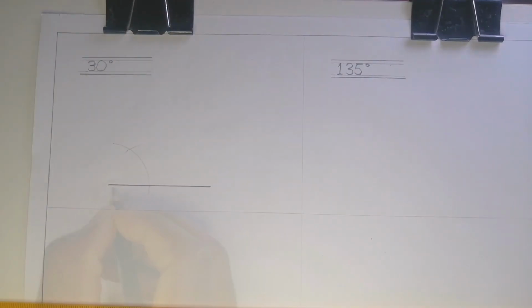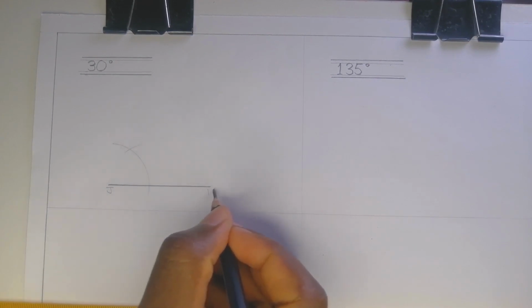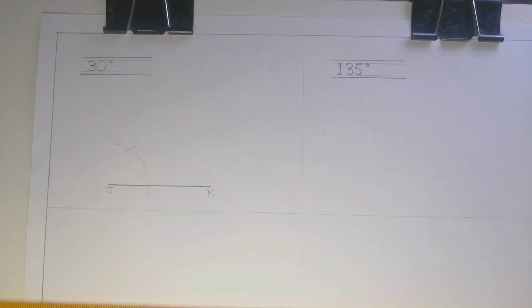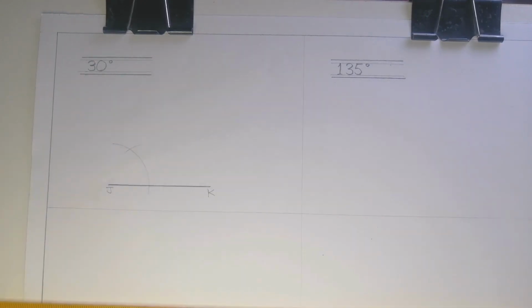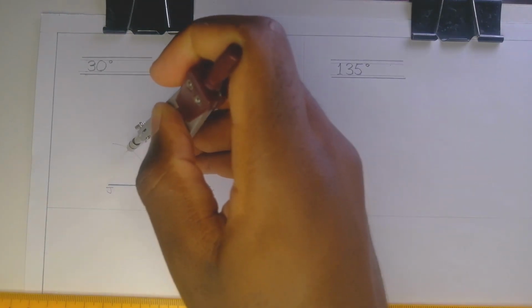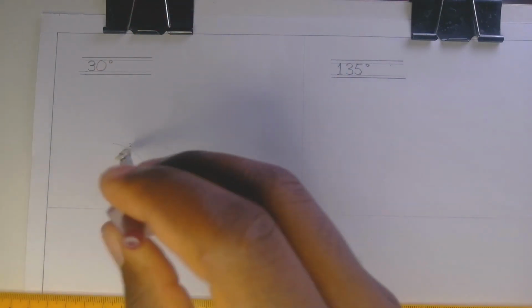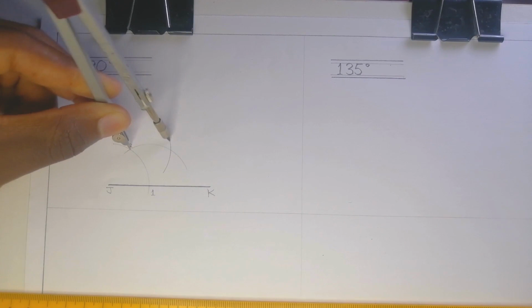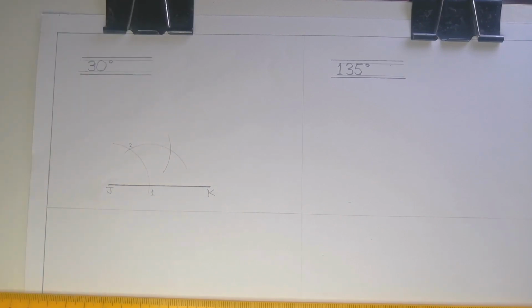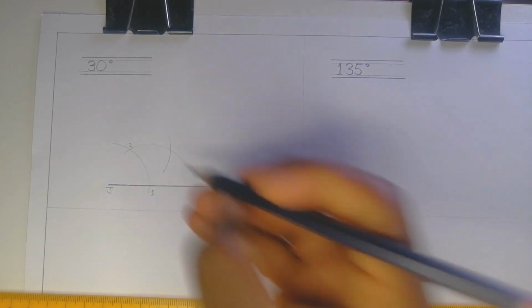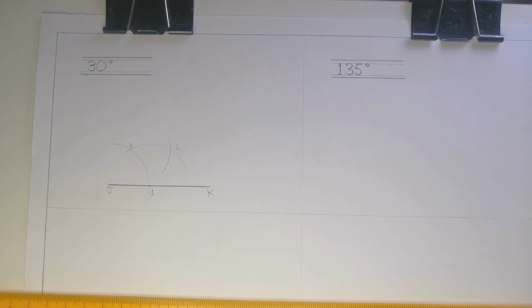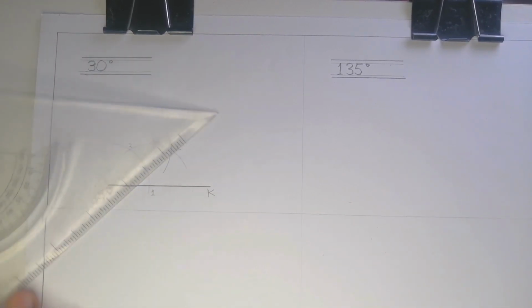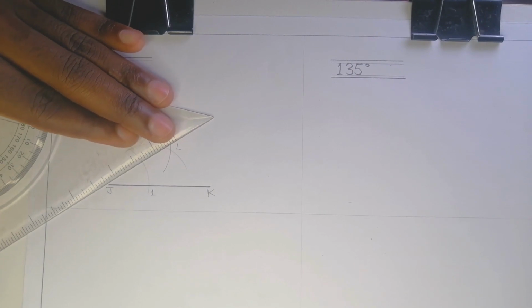So I've constructed it. This is J and this other one is K. I could draw a line from J passing through that point, but there's no need. Pen in my compass to point 2. Notice I will be using the same arc, and then I'll stand at point 2 without changing my radius. I'll make another mark like that, and then this new point that I have here, we can call it L, is going to give me the point that I need to make that 30 degrees.